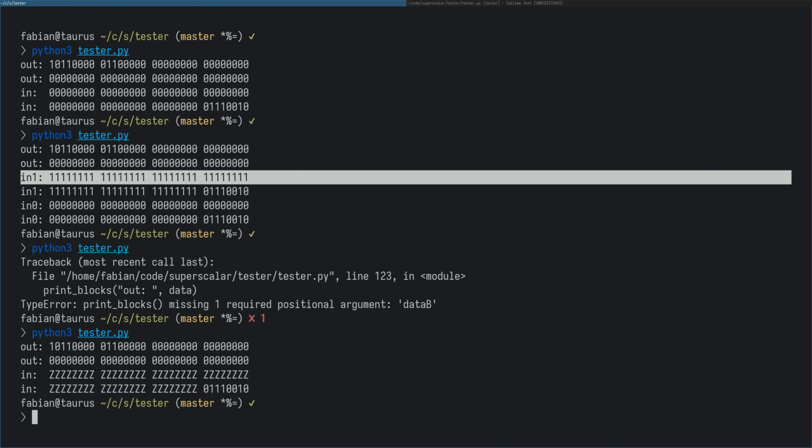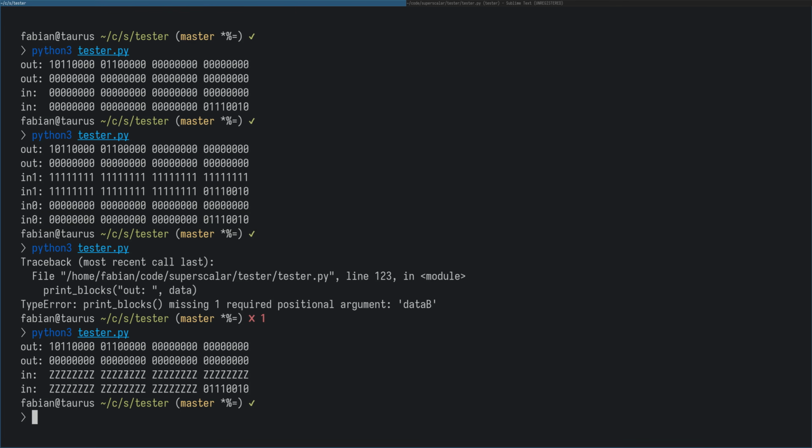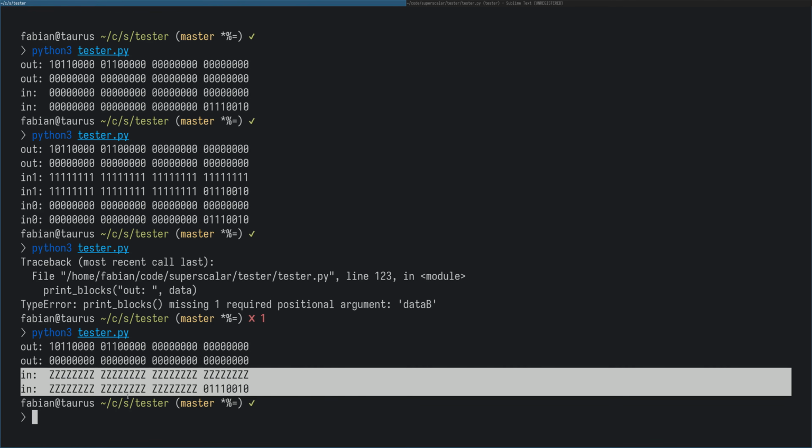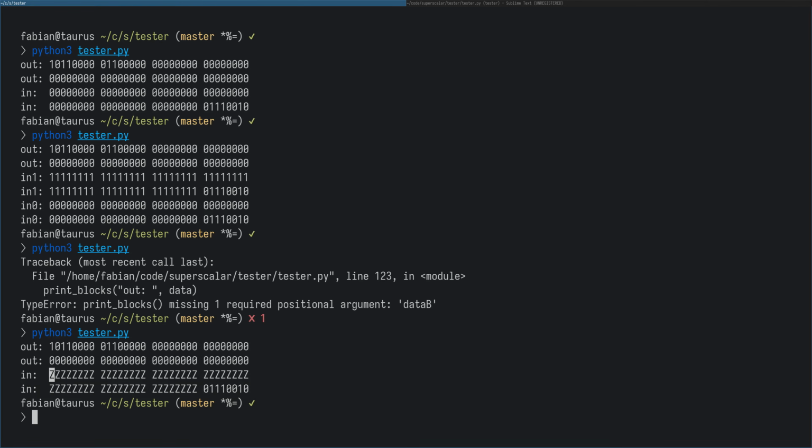So as you can see, these 2 separate reads here, we've now combined into a single output, and we're using this discrepancy detection between the first and the second read to basically indicate where the high impedance states are. And so all of the inputs that we have disconnected in actual physical hardware read as a Z, as a high impedance input. And the only thing that shows up as actual proper ones and zeros is the multiplier output, which is the one we've actually connected. And so what we can do now is we can connect some random inputs on the tester PCB to VDD and ground and actually see them show up.